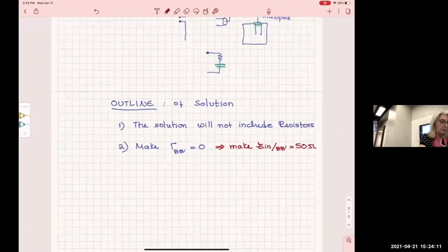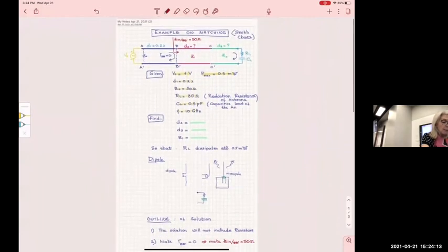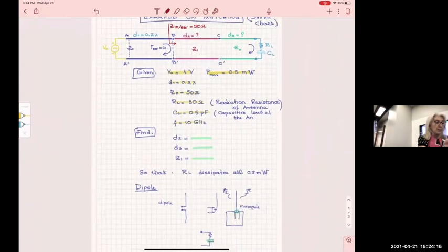That's the other thing, all right? So now I'm getting a little closer, since I know how much my Z input at BB prime has to be: 50 ohms. I don't care about the blue anymore. Now I'm concentrated on the red and the green sections. If my Z1, since I cannot add anything, that means forget about stubs, because stubs is something that you will have to add.